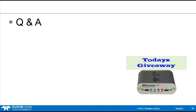On slide 96, the PD cable provided by Lecroy is to be used to spoof the controller. How do we test our cable functionality if it's working properly? Well, this is a case where you would want to use the Teledyne Lecroy power delivery exerciser. This is built into the Voyager platform, and it's a full-blown, scriptable exerciser that can communicate over Type-C to power delivery endpoints, including source, sink, and cable endpoints.